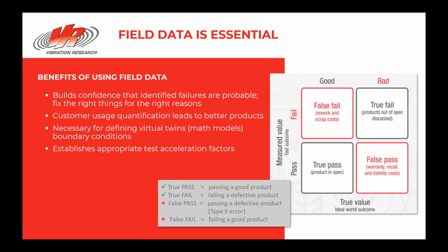The common standards today vary significantly in terms of frequency, anywhere from 7 to 200 hertz or 8 to 1,000 hertz, etc. Amplitudes that vary by axis, durations from 3 hours per axis to 38 hours per axis, industry standards that include sine sweeps or are just random or both, mechanical shocks that have 150 Gs, 6 milliseconds, or 10 Gs for 16 milliseconds, and the number of shocks, 3, 10, who knows? So which of these is right for you?